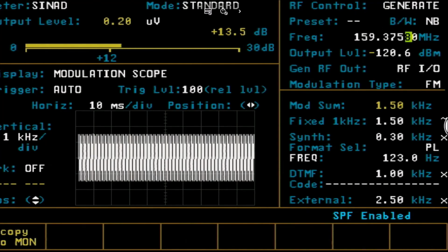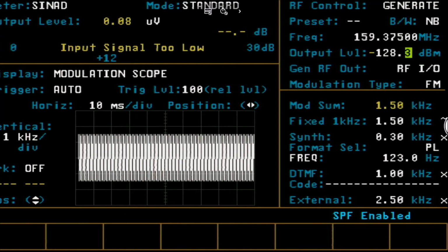And now you can go back down and go the other way and confirm that, yeah, I'm definitely getting worse as I go down. So that was an accurate reading there. We'll go plus 140 hertz for our frequency error.